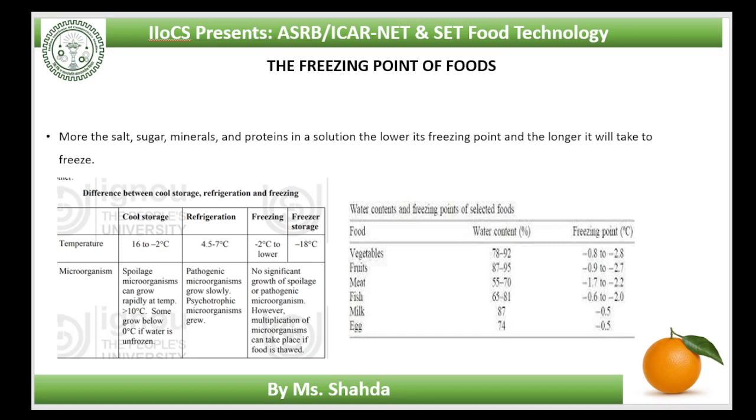The freezing process is thus a process of lowering the product temperature from its original value to the storage temperature. From each point, the heat must be removed by conduction to the surface of the food. The surface heat is then removed to the refrigeration medium. The freezing time depends upon a number of factors such as dimensions, shape of product, thermal properties, and temperature of the refrigerant medium.